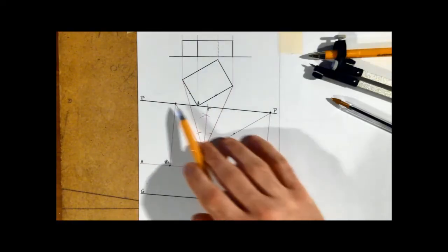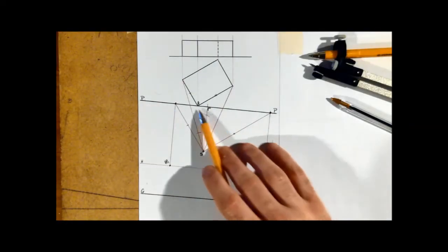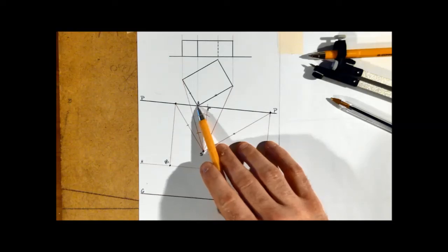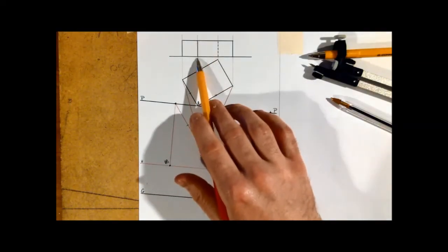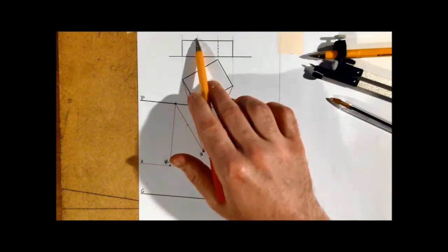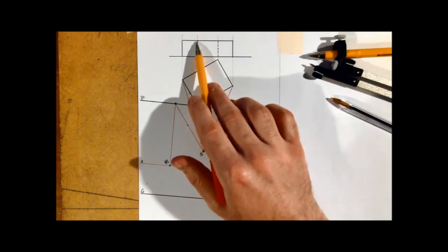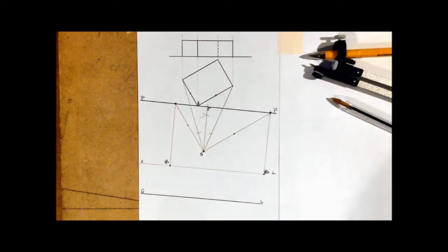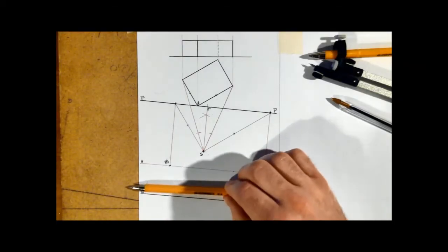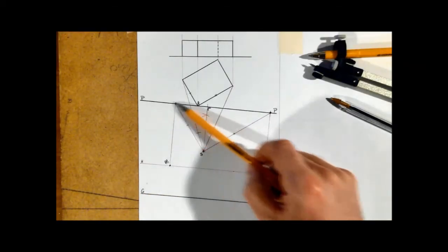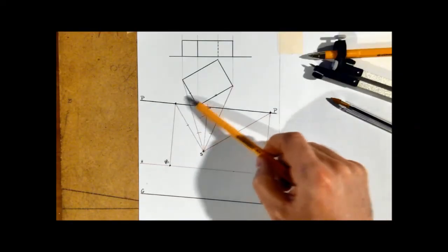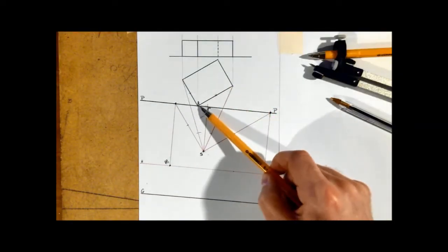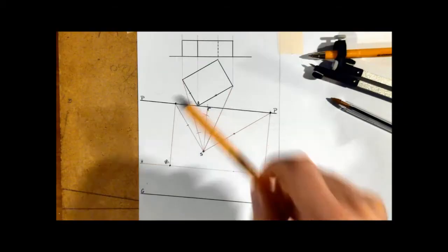Okay, so in this case our picture plane passes through the corner A, which is this edge right here, and if we look up at our elevation, imagine our A is down here on the ground and it has a height of 15 millimeters from here up to here. So the overall height of it is 15 millimeters. The only place that I can take true lengths from is when the picture plane is passing through any part of this object. In this case it's touching right here at the corner A.